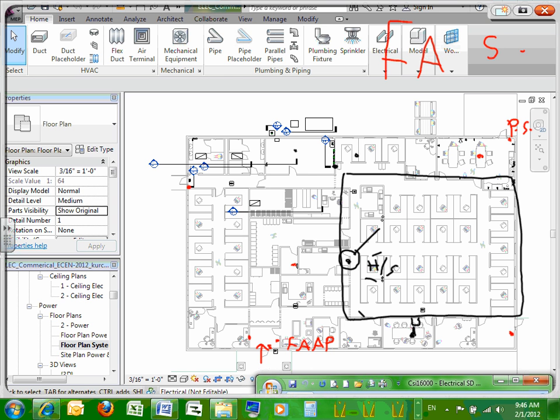Smoke detection throughout the entire building. So you need complete smoke coverage throughout the entire building, which means smoke detectors need to be placed to cover this entire open office area. I'm just kind of guessing with coverage here, but I think you also got some coverage.